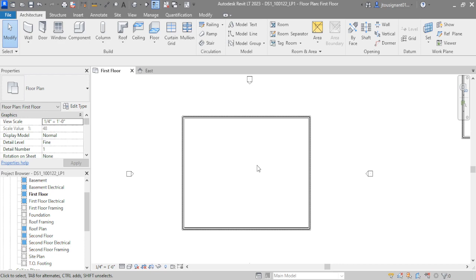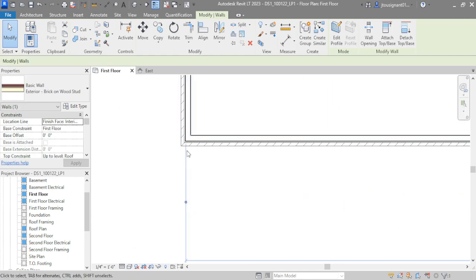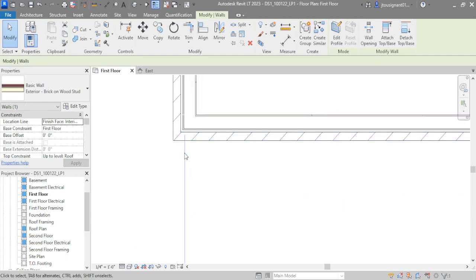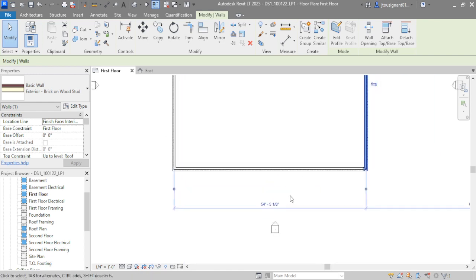So, did I have location line going just now in the proper spot? Did I draw that correctly? Did I type in the right numbers? Is there a way right now to verify that I drew those the right ways? If you're saying temporary dimensions, if I click on that, the temporary dimensions are of course by default going to wall center line because that's the most helpful location for us. That's sarcasm. It's bad. It's not good. So we can't verify that.